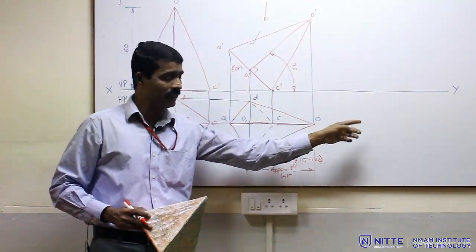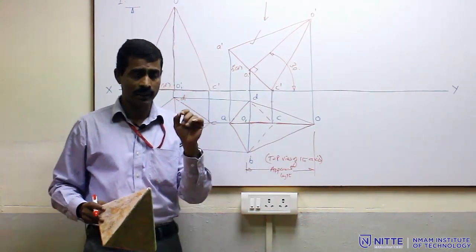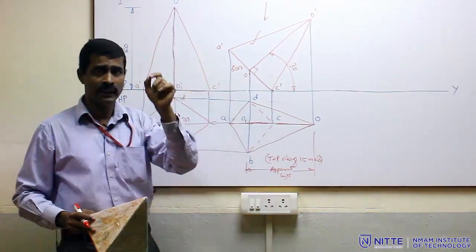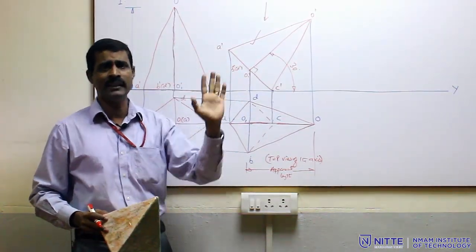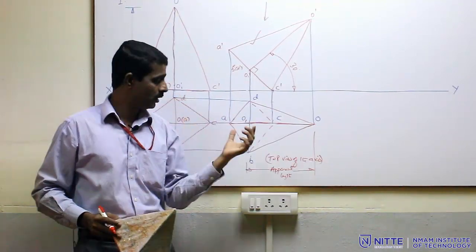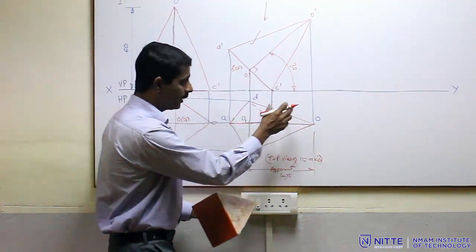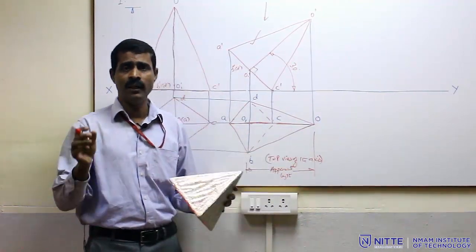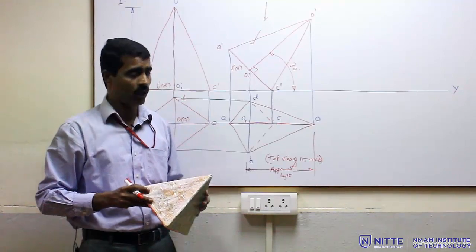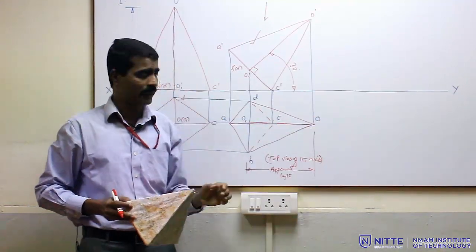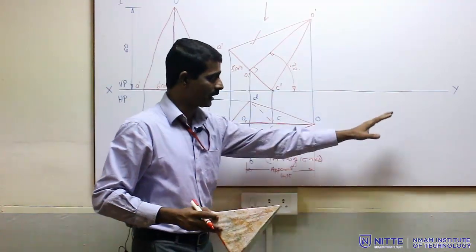But the given inclination is true. How can we understand the true inclination? You read the question, it is mentioned that the axis is inclined. If an axis or line is inclined, it means it is a true inclination. But the axis we have here is apparent, and we are going to rotate this particular view to satisfy the VP condition. So we cannot go for 60 degree now, because 60 degree is the actual inclination, but the length we have is apparent. So we need to do some construction here.